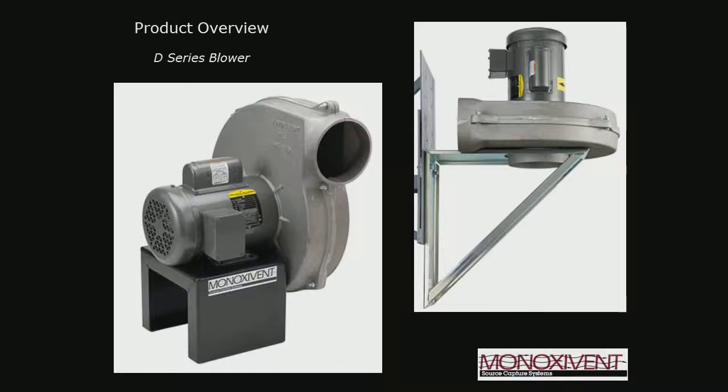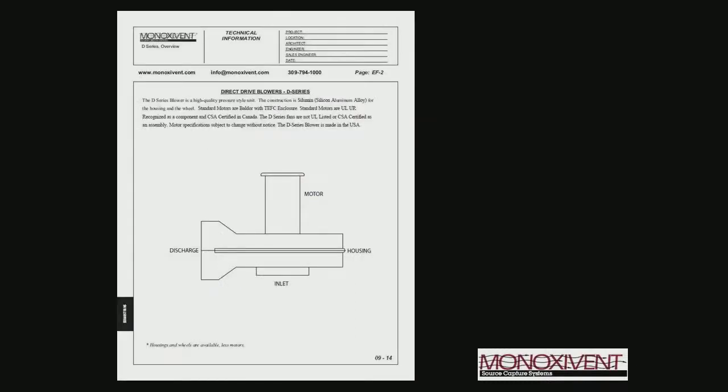Once we've determined what the CFM is going to be, as well as the static pressure, then we can move on to selecting a fan. The first fan that we have here is our D-series blower. It's a simple cast aluminum wheel, cast aluminum housing, and a drive motor. Very simple. The motor is a UR labeled motor, meaning it's recognized by UL as an electrical component for a system. However, these fans are not UL listed as an assembly.